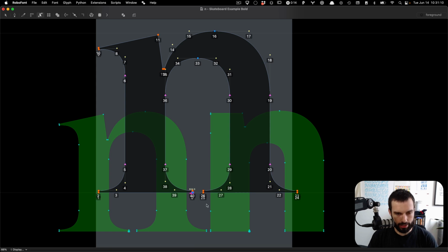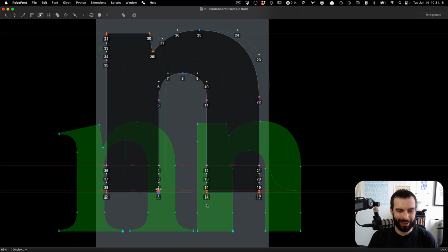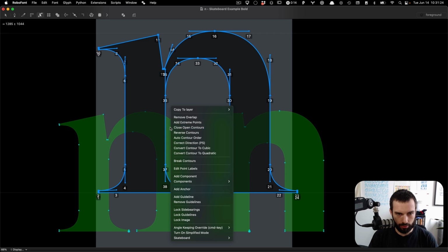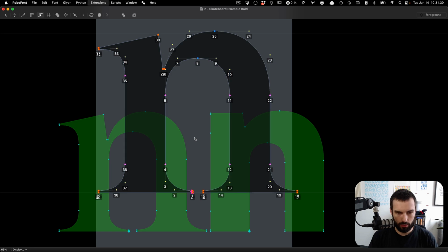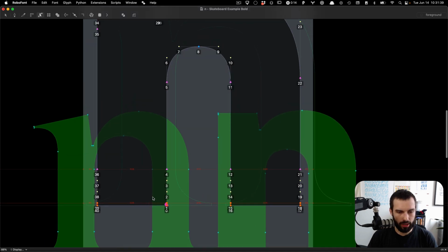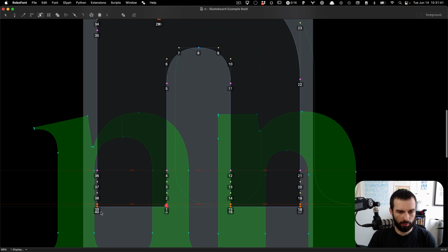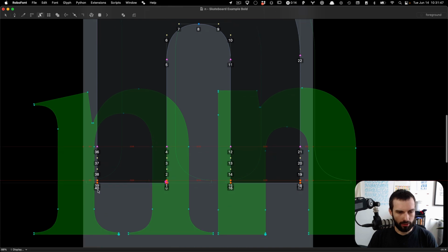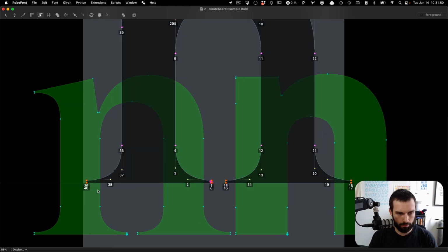So let me set this to be the start point, and I'm using another Eric von Blockland extension called Edit That Next Master to go between them. So master is another name for source. Reverse contours. Okay. So I'm clearly missing something here. At this point, I might start counting the points, and that's why I show the point indices sometimes. So there's 40 points here, 40 points there.